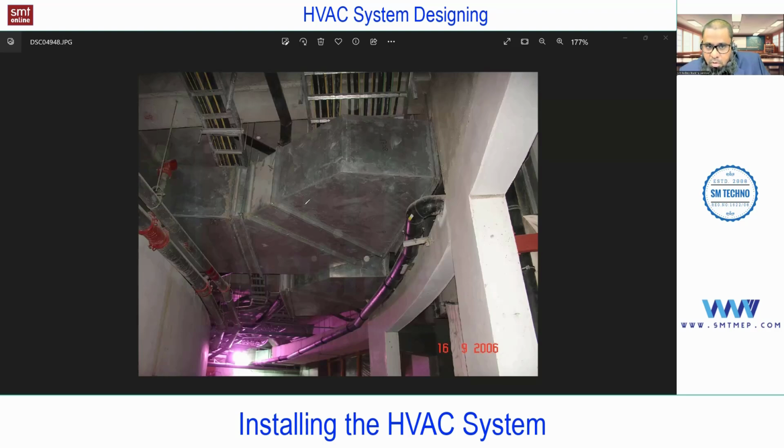First of all, in order to decide this, experience is required, and that's the reason in actual practice this decision is taken care of by the architect or senior mechanical or electrical engineers. Without experience, you cannot decide this. Above the false ceiling you'll find limited clearance, and in that clearance we need to fit all this. There is no question of reducing the cable tray height, because it is a standard. Even the firefighting pipes, distilled water pipe or drainage pipe, we don't have much scope to reduce, because it is based on the design.